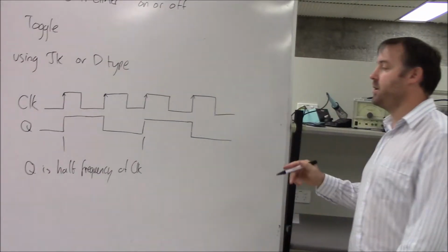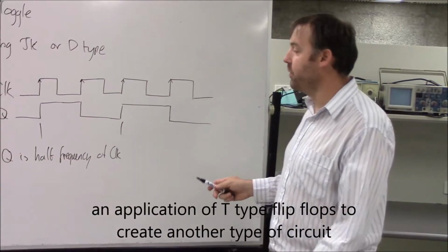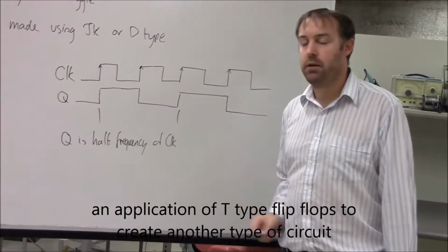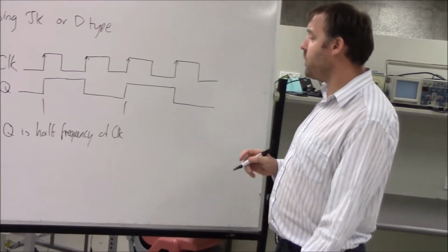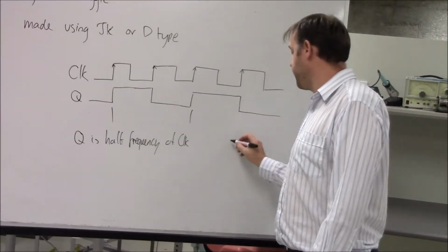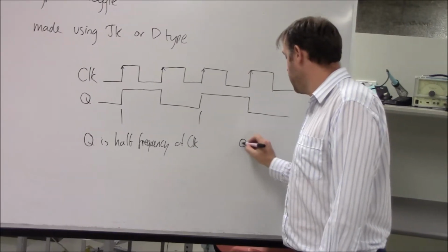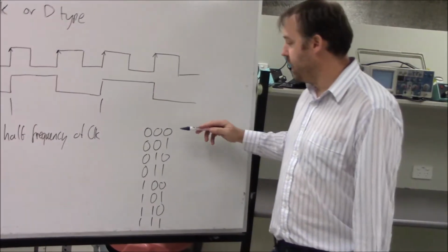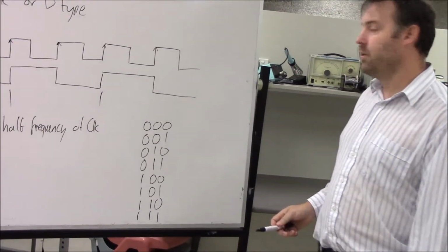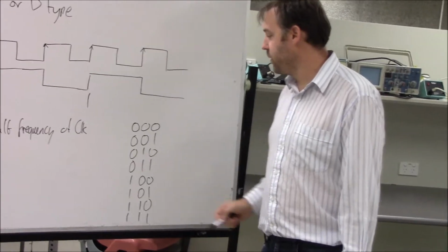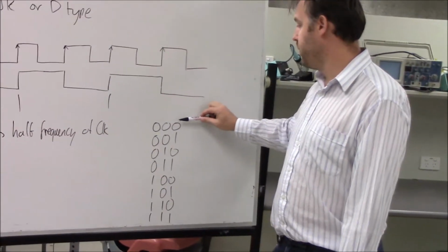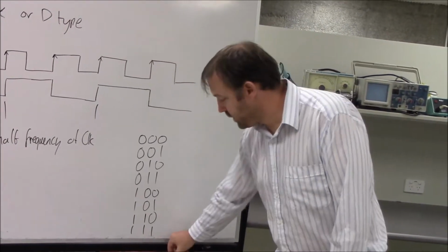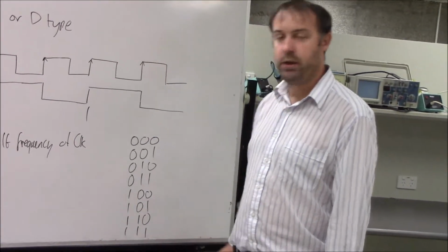Okay. Now this has a very important implication for counters. If you recall from the number systems video, if you look at 3-digit binary, so that's each possible state for our 3-bit number. So 2 to the 3, which is 8. So we've got 0, 1, 2, 3, 4, 5, 6, 7, and then it would go back to 0 again because we've run out of bits.